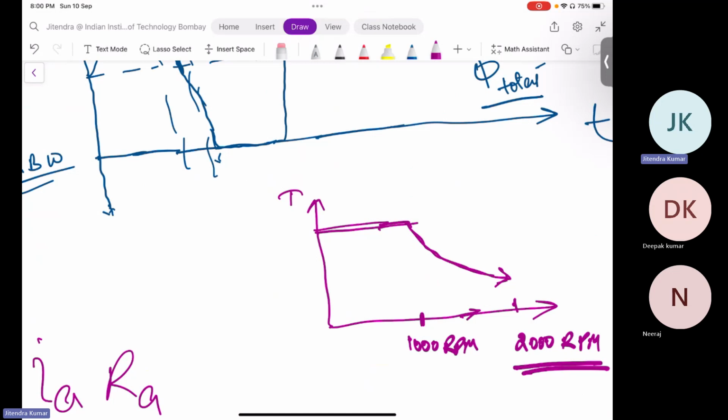Yes, even at 80 kmph, at 2000 RPM, you need very small torque, and that it is already providing. You don't need higher than this torque. This is the low torque characteristic of traction application. As you go to higher speed, you don't need high torque. Your torque requirement reduces, and that is fine. And that is what field weakening does. I hope you are getting my point. So it is fine for electric vehicle application, but it is not fine for fan or pump application or any other application.